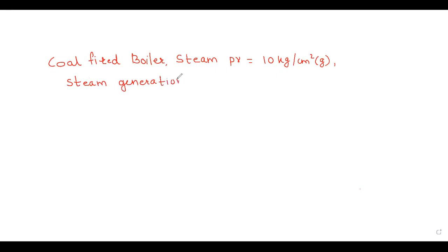Now how is that recorded? As I said, as a boiler auditor, you need to record the steam flow meter reading, or you need to record the feed water temperature and feed water flow rate. Both readings are perfectly valid, because mass of the water is equal to mass of the steam generated. So whichever way you get it, that is the correct reading. So this is the 8 tons per hour reading which has been noted down.